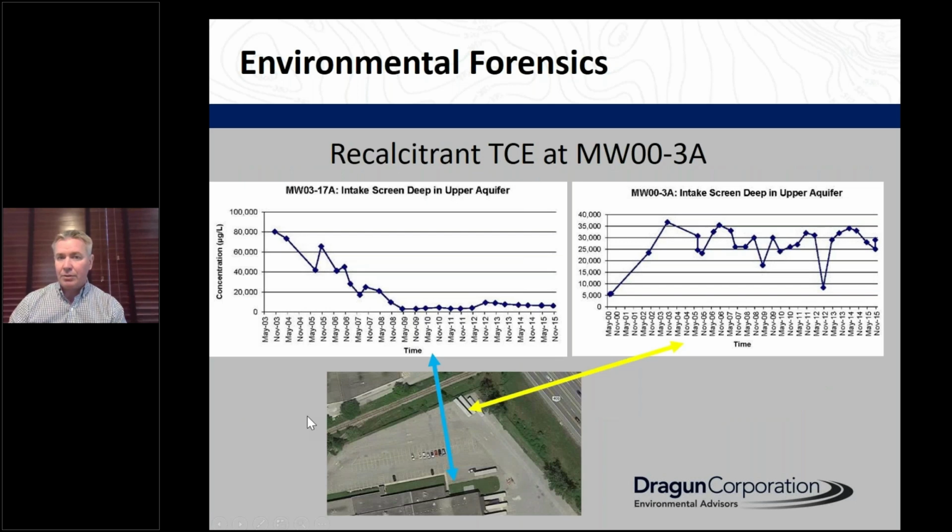After about a dozen years of remediation and monitoring, most of the wells on our site showed a significant downward concentration trend, as shown in the graph to the left. Based on this and the risk assessment that supported it, we proposed to mothball the failing remediation system and move to a monitored natural attenuation remedy.